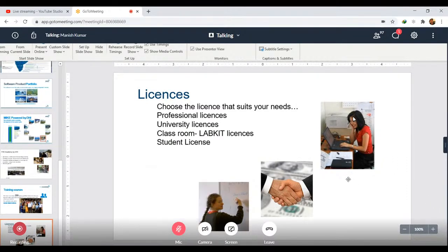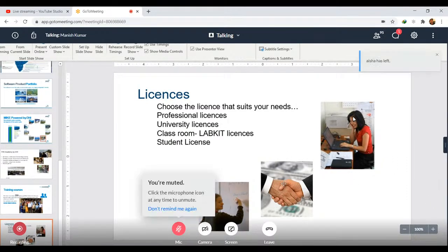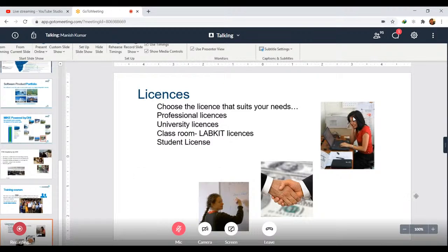You can always start your model, and then do a quick little survey. You can get information from Google Earth Pro, like building structures. You can also provide information, like if it's a 2-story or 3-story building, then you can give heights, like 5 meters or 10 meters, to those grid values where you have building profiles.